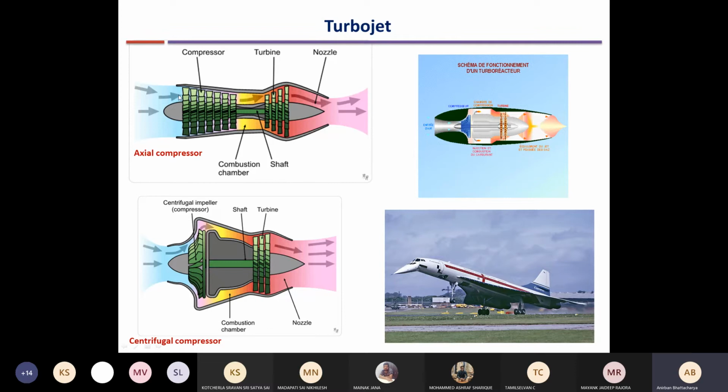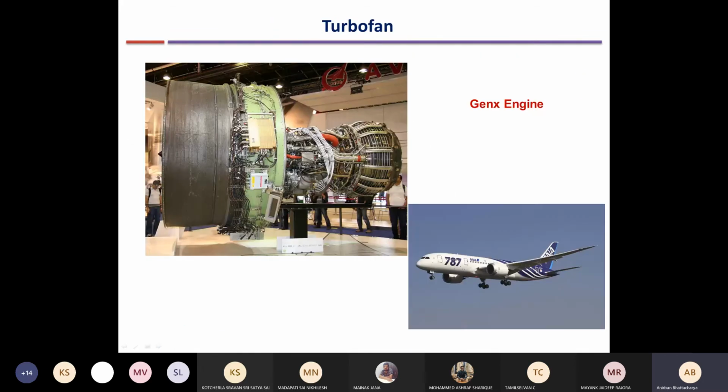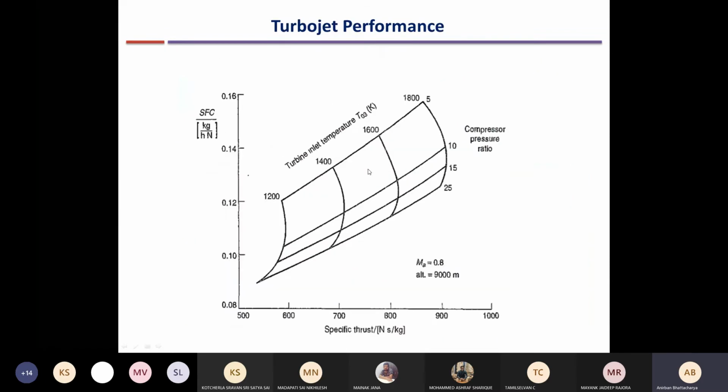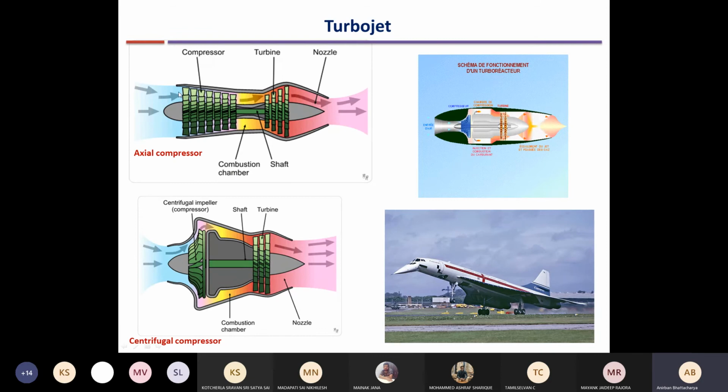At the inlet, unlike industrial gas turbines, before the compressor, there is another region. It is not shown here clearly. Okay, I think I have shown you for the turbofan like this. So this part, it is not clear from here, but this is very carefully designed. Okay, slightly, the area is increasing as you go inside. So this is actually a diffuser. Okay, so a diffuser is there before the compressor. So in this case, this is a turbofan, there is a fan, but for a turbojet, there will be a diffuser. A diffuser is exactly the opposite of a nozzle.